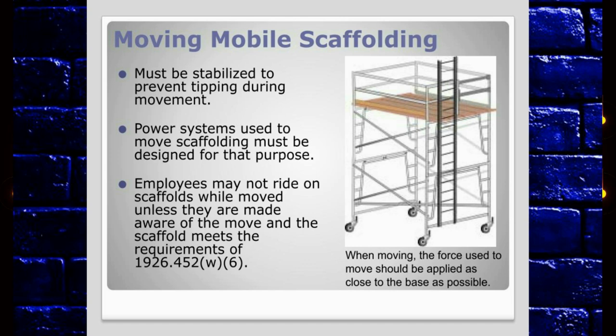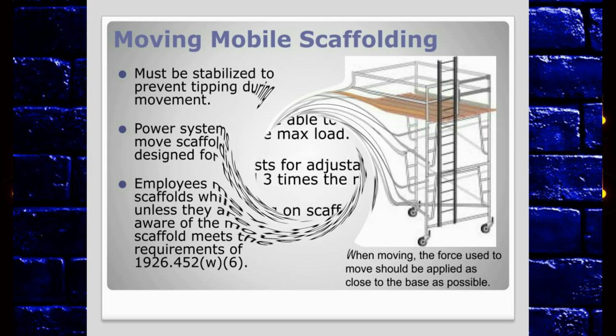Employees may not ride on scaffolds while moved unless they are made aware of the move and the scaffold meets the requirements of 1926.452. So I guess if you hold on really good and you're where it's moving, it's okay. When moving, the force used to move should be applied as close to the base as possible.